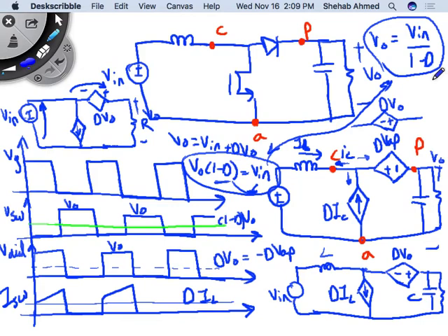So this is like 214 to 420, all in one slide. This is now putting everything together, right? This is you designing a simple converter, of course you can have very complicated converters, but you went all the way from your steady state analysis to switch model to dynamic transfer function to steady state again to confirm that you're doing everything correctly.